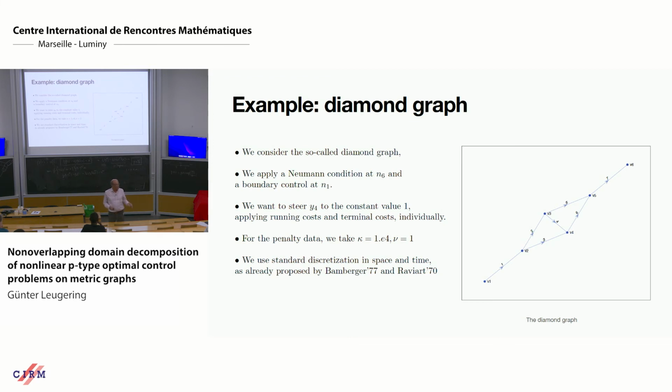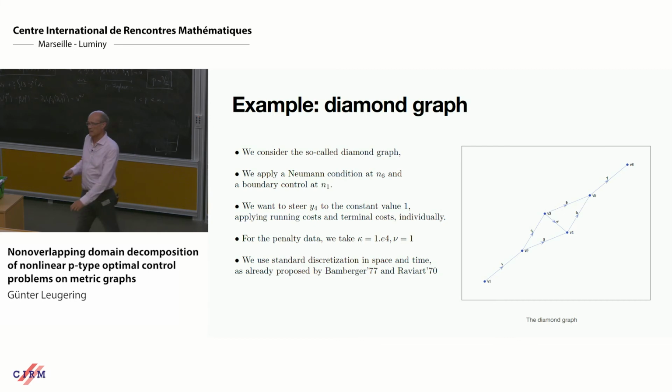And if you can do that, then you decompose optimization problems. This is nice because then you can use standard optimization software for the subdomain problem, right? And I use IPOPT all the time, with CasADi, which is also an automatic differentiation tool.